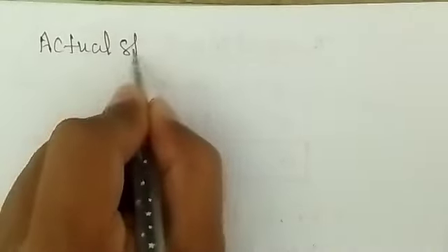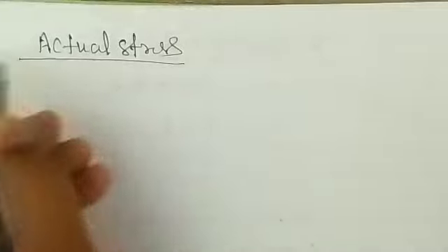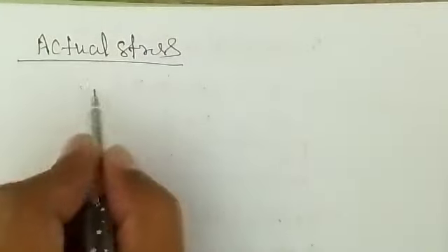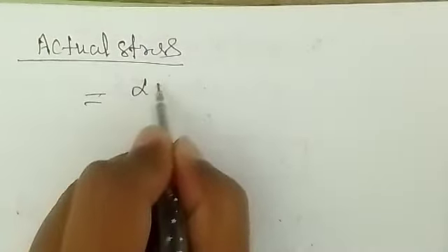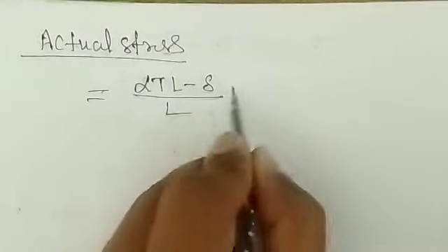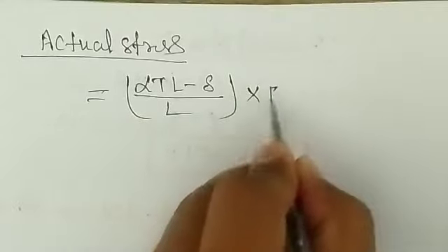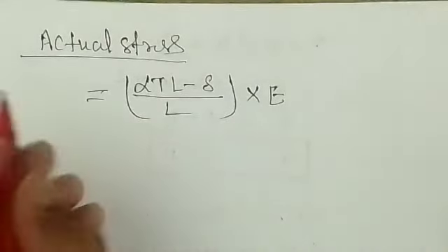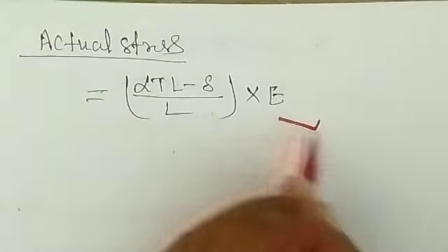The actual stress is the actual strain into Young's modulus, that is alpha TL minus delta by L into Young's modulus, right? So we got the actual stress.